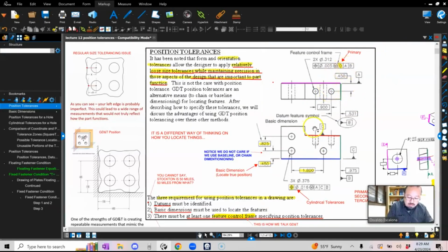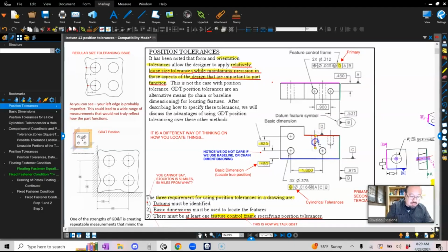These are the holes that I'm doing. And again, it's this one axis. This is the axis, this is the axis. These are the two holes. I'm controlling the position with respect to Datum A and Datum B, as you see right there, and I'm orienting it with Datum D, and Datum D seems to me is this surface, the one that is red.